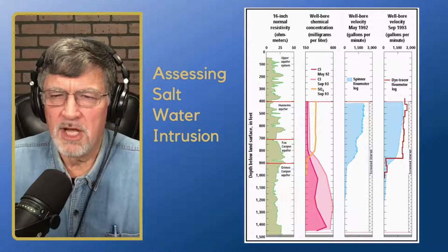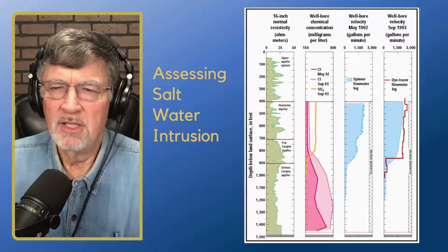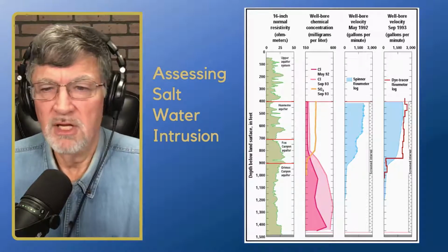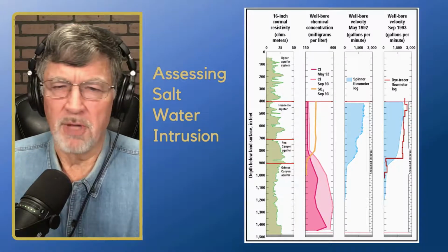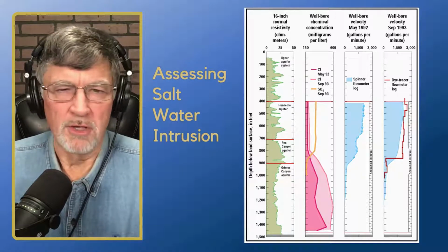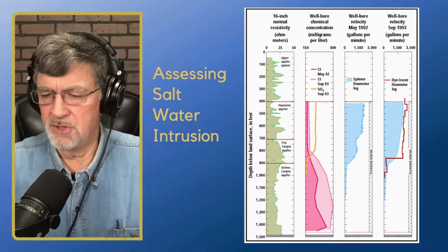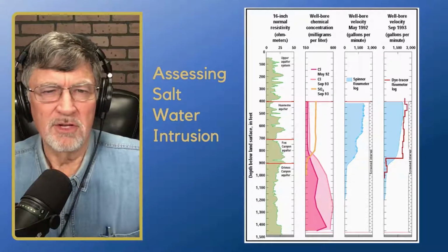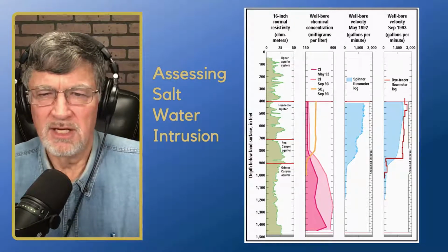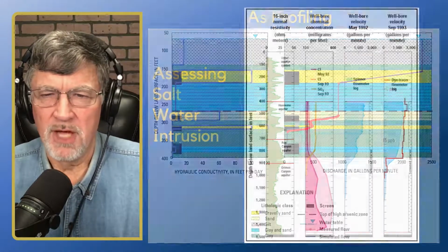So we just take things above that, because then you're going to get clean water and your best flows. Literally no flow at all is coming from the high chloride zone down deep. It's stagnant, salty water, so we don't want to take that anyway. So this shows the value of that. And this could really be any type of contaminant. This is just a handy dandy USGS study that I had and wanted to show to you.